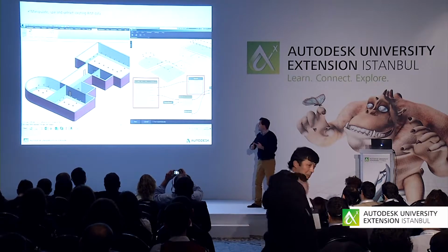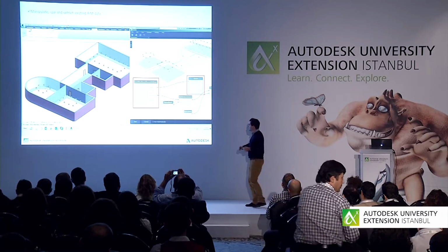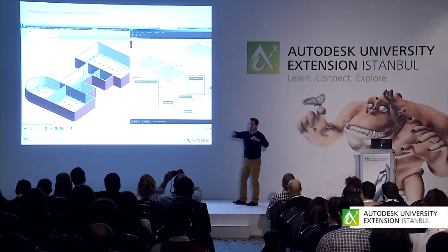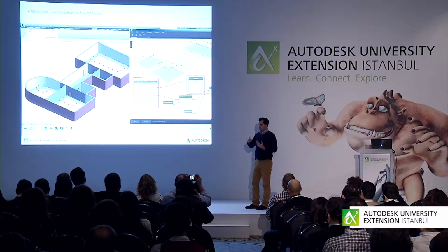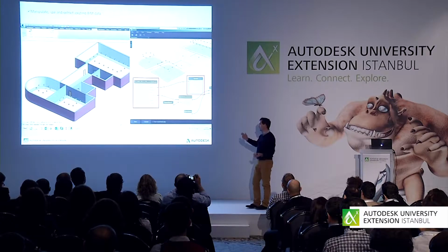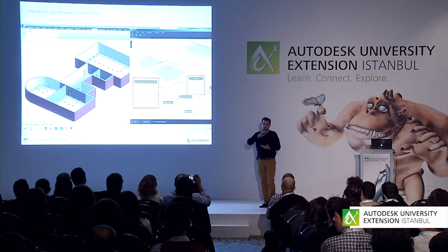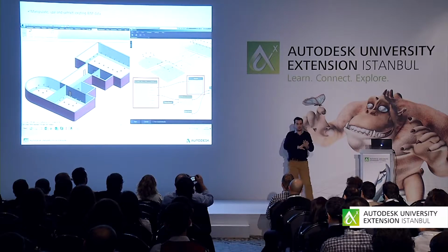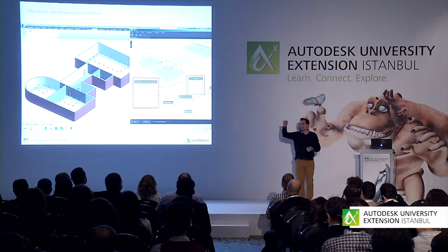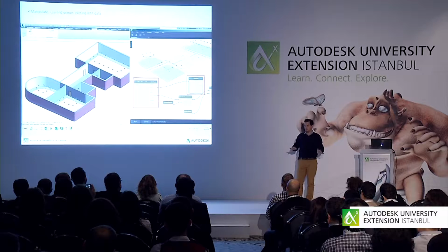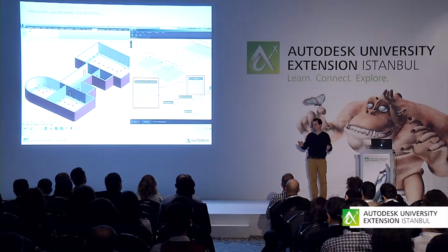Okay, so the names, numbers, but also, what is very important, the boundaries. So you get the polylines of your rooms inserted into the rooms. And then using Dynamo tools, you can create unlimited things with that. Because you can, for example, add and control very easily and very effectively what kind of finishing floors you have in certain rooms. Like you can search through the name of the rooms and assign the correct finishing floor in that room.